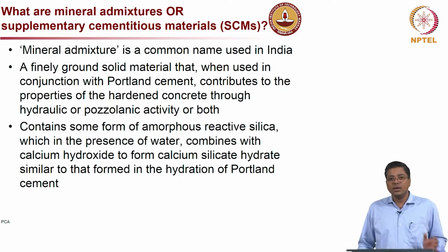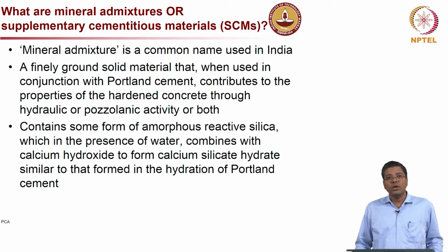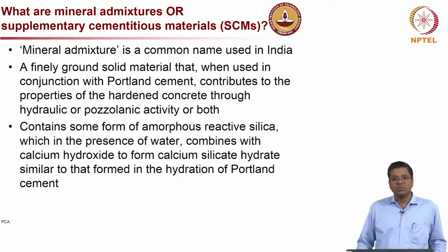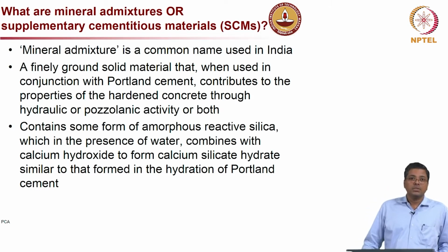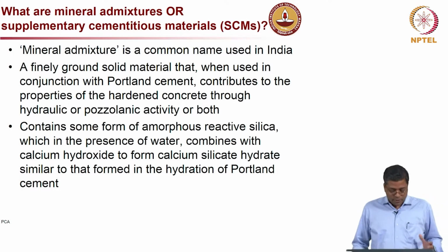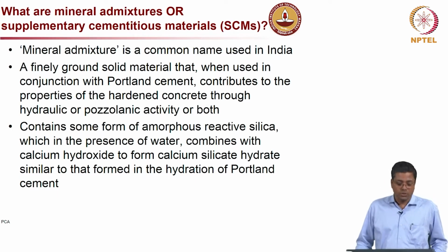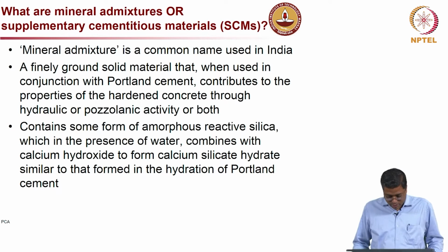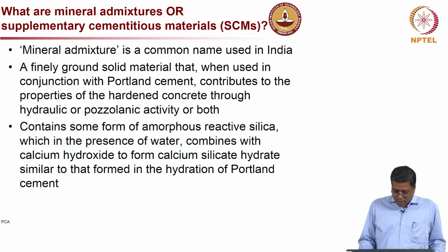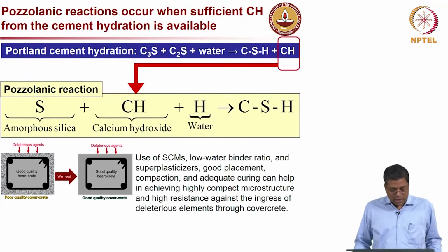The main component we are looking for in SCMs is the amorphous or reactive silica, which in the presence of water combines with calcium hydroxide to form calcium silicate hydrate, which is basically the glue you are talking about in cement hydration.